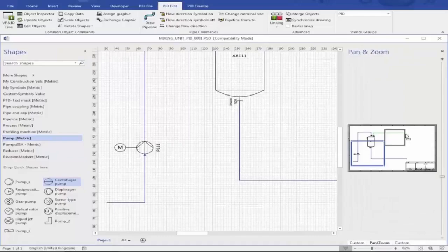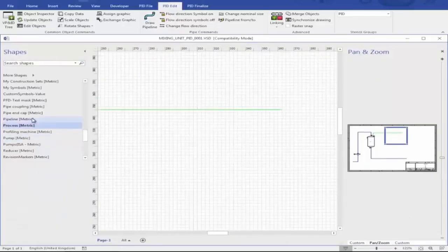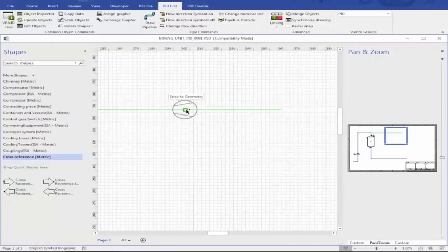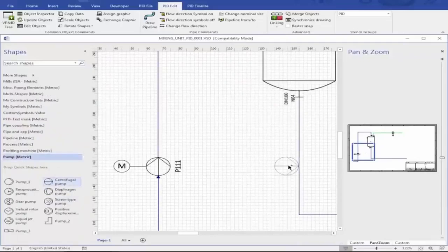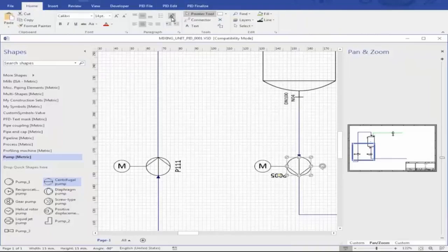This is the same for other object placement. For example, placing a compressor on another pipeline with a motor connected to it as a child object. And then we are going to place one more pump on the pipeline coming outside of this vessel. Using control points, we can easily move the objects and we can define the rotation of the text which is there on your objects.